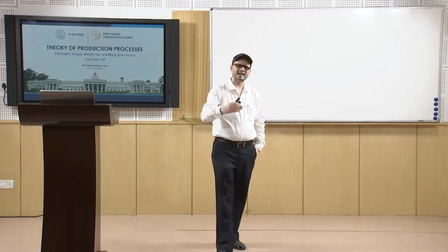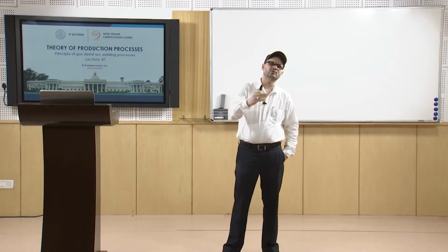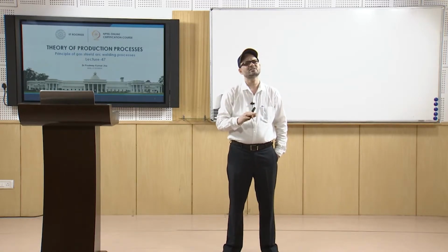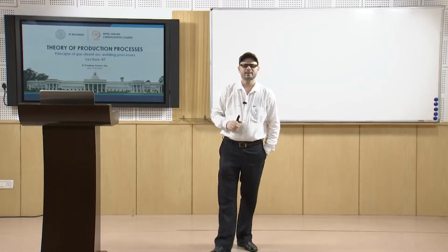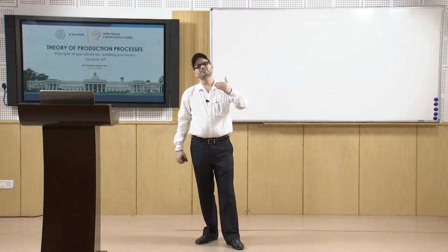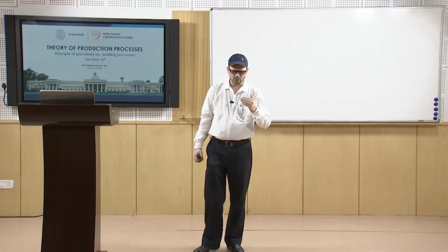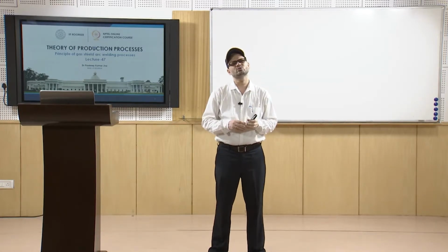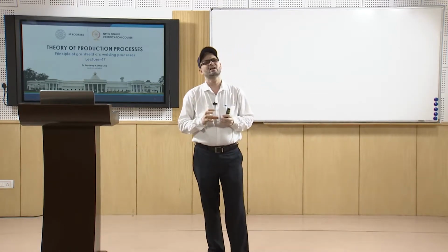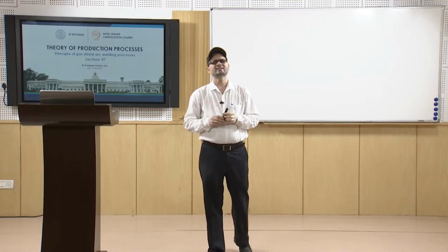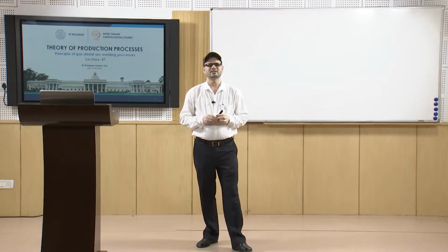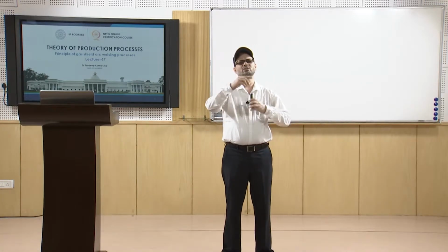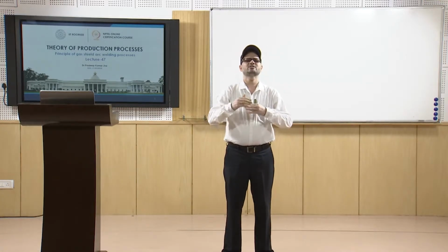So, when these tungsten electrodes are used for that, we call it gas tungsten arc welding. Then another variety is that we use the gases, but we also use electrodes which are consumable. In that case you will have the metal inert gas, known as MIG.